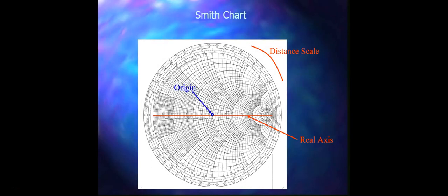Now next is the Smith chart. A Smith chart is used by manufacturers to characterize the impedance of a radio frequency system on data sheets, and it helps us determine multiple parameters, for example impedances, admittance, reflection coefficient, noise figure, gain contour, mechanical vibrations, etc. On the screen you see this origin. This origin represents an impedance equal to the characteristic impedance of the system.